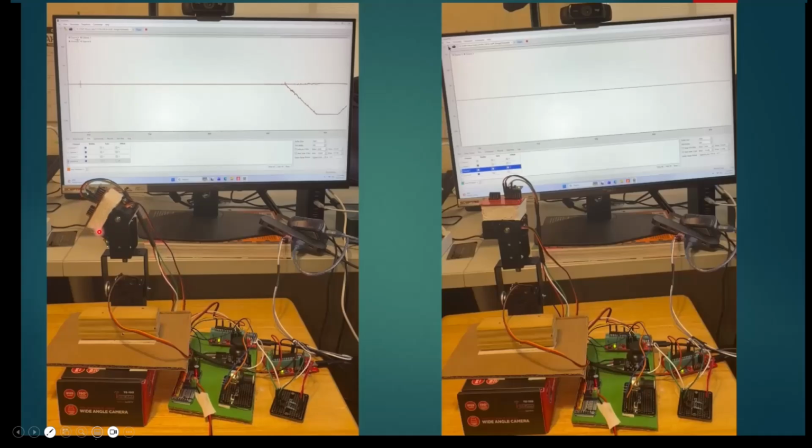The servo motor just goes back and forth. The output from the IMU goes to the serial interface over USB to this program, which is a serial plotter, and you can see here the output of the signals. We have to put this in a certain format that I'll show you once we go through the code. The main program actually does that.